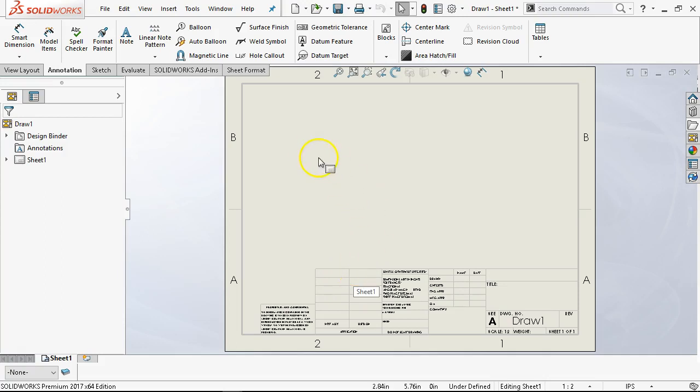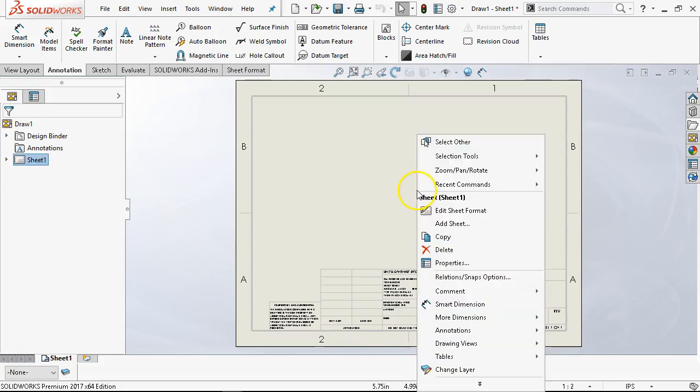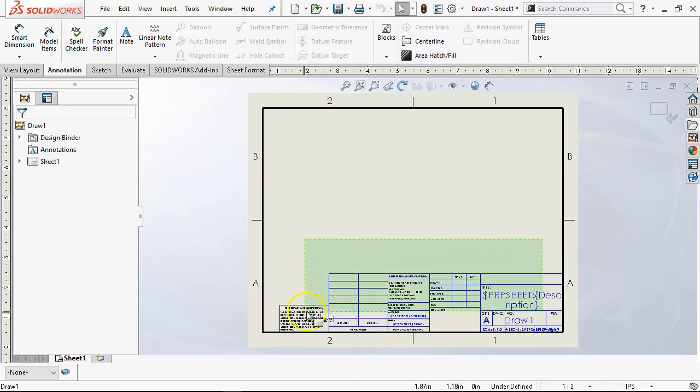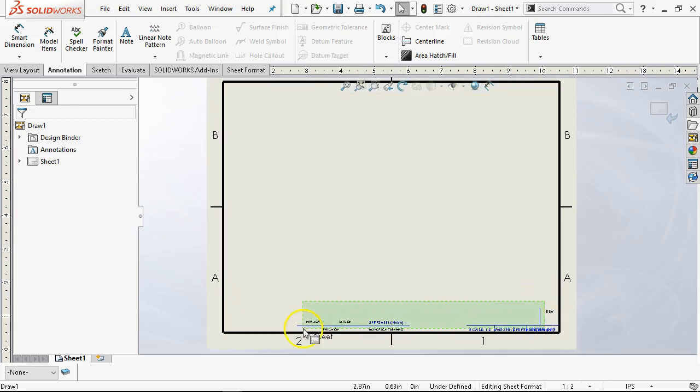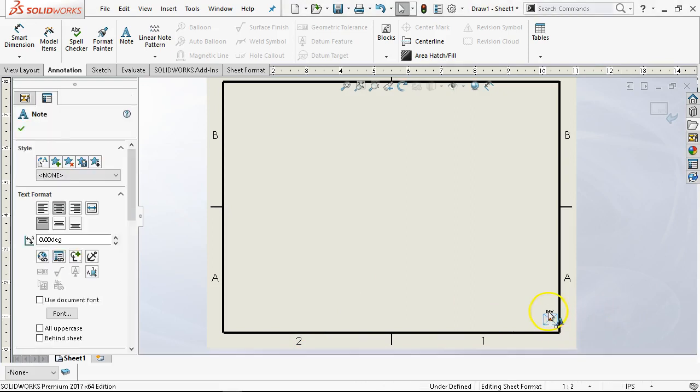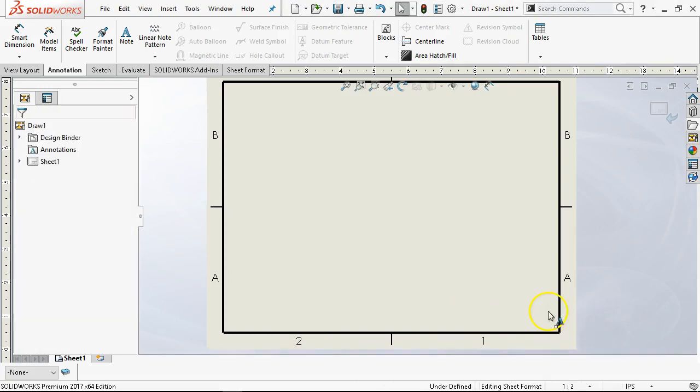So last time I went through and I selected a blank drawing template, and it had a scale factor in it, so the limits were pretty much around that scale. When we go into editing, one of the things that we can do is edit the sheet format. That will give us access to all of this, but I really don't want to do that every time. All right, getting rid of the geometry. So this will be our simplest drawing template.